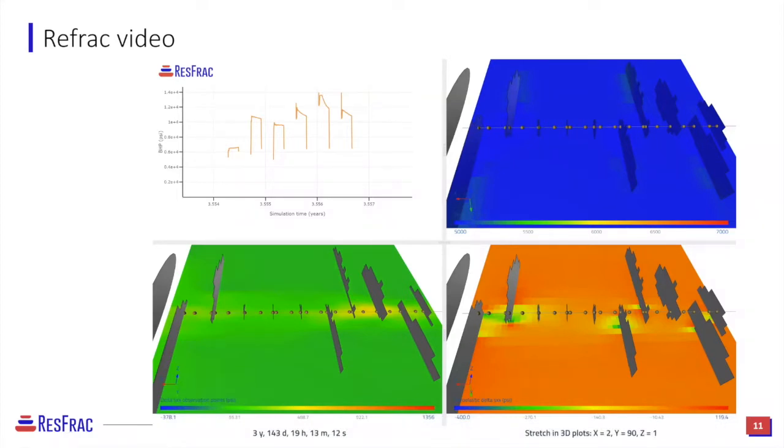And so the stress shadow from aperture will never go back to 0 as long as there's proppant that's wedging those walls apart. That's what we see in this yellow portion over here: along the lateral where you have the most proppant, there is some degree of stress shadow that is locked in.